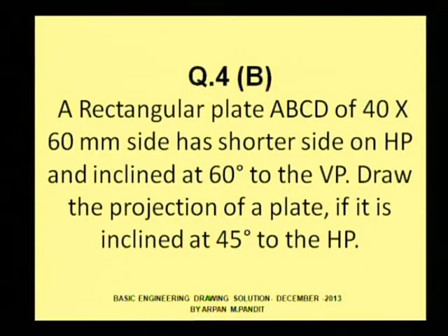Our next problem is from the projections of plane, in which we have been given that a rectangular plate of 40 by 60 mm is resting on HP on shorter side, inclined to HP on 60 degrees, and we need to draw the projections of this plate. We will see how we can draw these projections of plane.